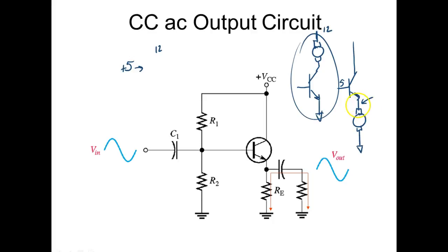And by the way, we would probably come up and do this. Why would we do that? We call those counter EMF diodes. Why? They protect your transistor so your motor can't generate back into your transistor.